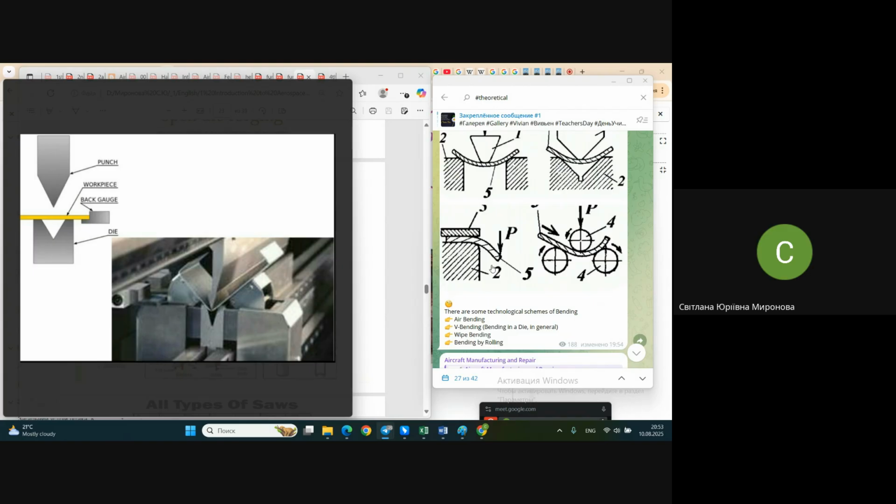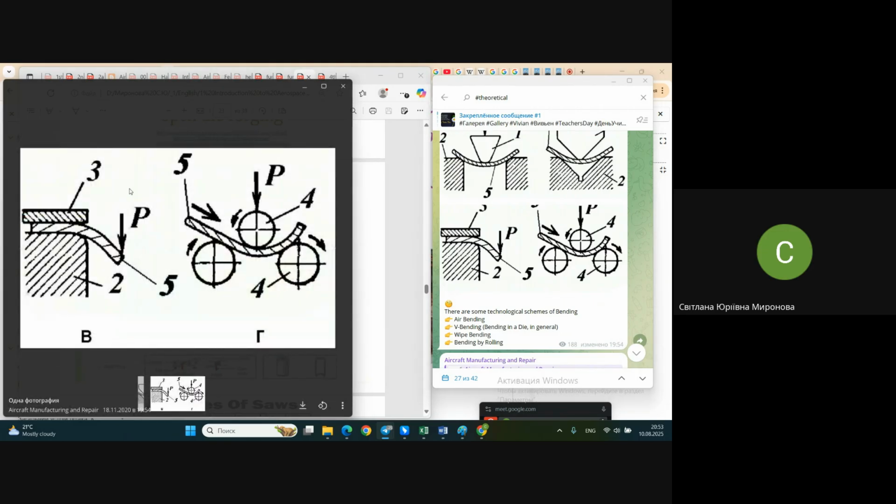Maybe it uses a completely universal thing. The die block you need in this case should have at least the same angle and the same radii as the part. You have a clamp here, number 3, but you have no punch at all, and it saves money.